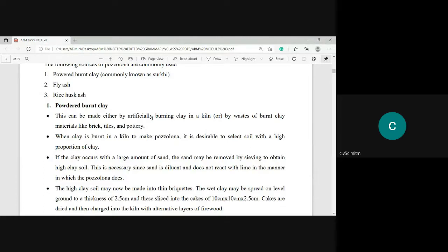produced. So those materials, that means, for example, if the brick is overburned, if the tile is not of proper shape, that is Mangalore tiles, not vitrified or ceramic tiles, or potteries of clay material. If this clay material is not intended to use for construction, because of its size, because of its other deficiencies, that material which cannot be used as a construction material, instead of wasting it, I can powder it, I can burn it, and I can go ahead with producing the pozzolanic material.